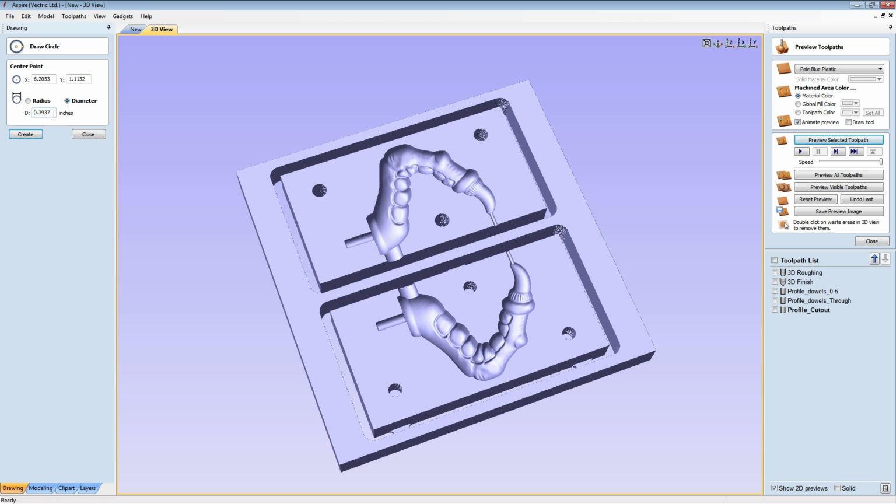If you're working in metric and you wanted to go the other way, then what you would do is you would type the inch value and then the multiply, the asterisk again, and then you would type M in order to convert that to metric, and again hitting the equals. Just to reiterate that, put the metric value in if I'm working in inches, multiply I to say I want to convert it to inches, and then hit equals on the keyboard in order to do the calculation there.